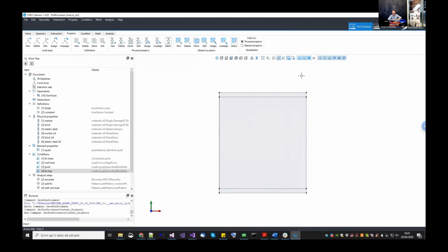Now, for the equivalent isotropic model, there are many ways you can compute the isotropic values. The most basic one is that if you have access to experimental tests over the entire masonry assembly, so you need the elastic properties, the tensile strength, in tension and compression, and so on. Now, in my case, since I was doing this numerical analysis, I used a concept called computational homogenization.